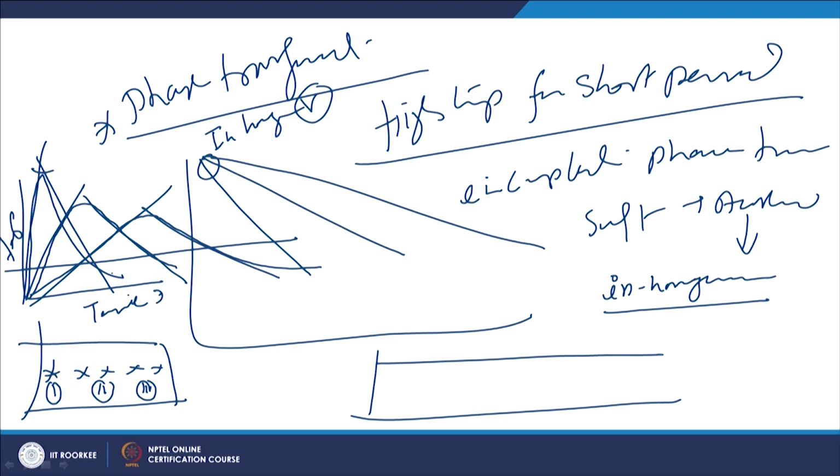And this homogeneity of the austenite is very important for the required phase transformation as per the composition of steel. But if it is not so, then it will lead to reduced hardening tendency, or reduced phase transformation tendency into the hard phases. So there are two aspects: the formation of inhomogeneous austenite, and as per the distance away from the fusion boundary, the cooling rates will be changing.